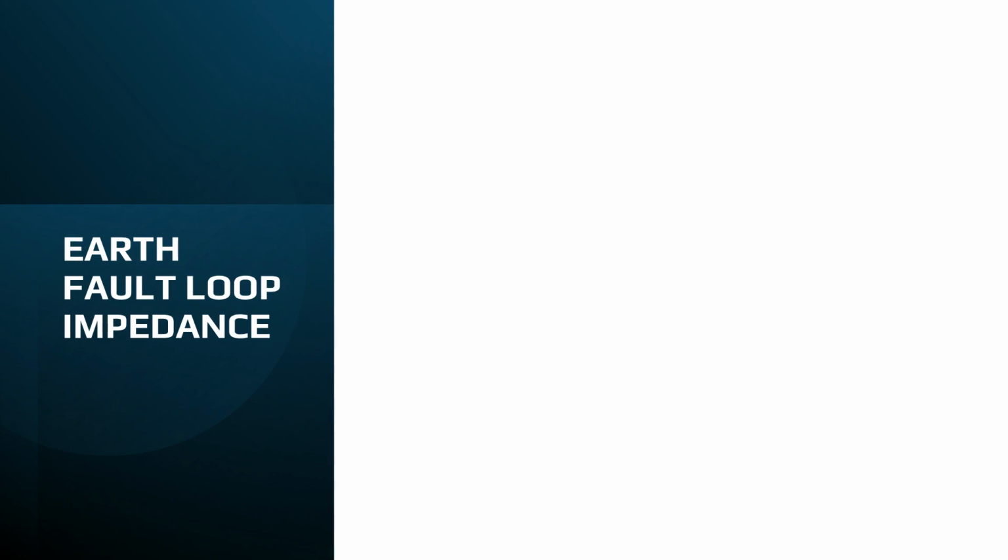Earth fault loop impedance, Zs, is a critical concept in electrical engineering, particularly in ensuring the safety and reliability of low-voltage electrical installations. It refers to the total impedance of the electrical path that a fault current would take in the event of an earth fault, from the point of the fault back to the source of supply. Understanding and measuring earth fault loop impedance is essential for ensuring that protective devices, e.g., circuit breakers or fuses, operate correctly to disconnect the supply in a fault condition, preventing electric shock, fire, or equipment damage.